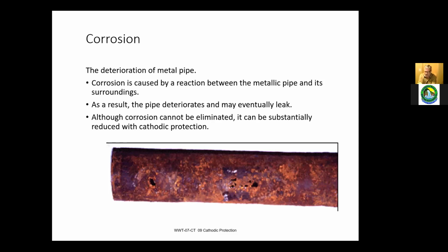We have an effluent line that travels from our facility to the lake. It's been in there since the 70s, 80s, sometime that was installed. And, you know, knock on wood, we've had no issues with it whatsoever. But that line is cathodic protected all the way through. Any tie-ins to that line are actually separated physically with a gasket or something else to prevent any corrosion of that pipe.